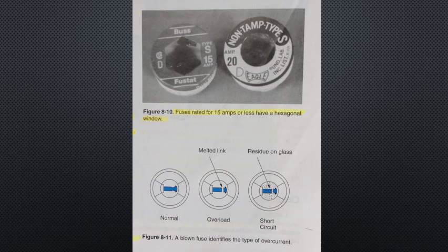Plug fuses are limited by the following voltage restrictions: maximum of 125 volts between conductors, or maximum of 150 volts between grounded and ungrounded conductors, or ungrounded conductors and the ground in grounded neutral systems. Edison based fuses are interchangeable. Fuses of greater current rating can be used in circuits of lesser capacities.